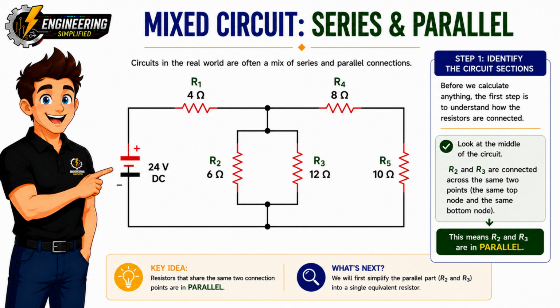Looking at this example, R2 and R3 are connected across the same 2 points, so they form a parallel branch. Meanwhile, R4 and R5 are connected end to end, with no branching between them, so they are in series. Finally, R1 is also in series with the rest of the circuit. By simplifying one section at a time, what looks like a complicated circuit becomes much easier to solve. Your challenge is to calculate the total resistance and the total current supplied by the 24-volt DC source. Let's work through it together, step by step.